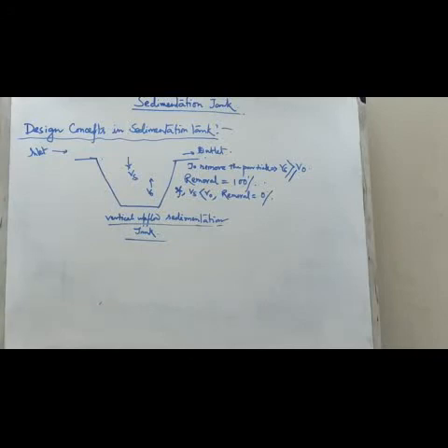Hence, for the successful design of a sedimentation tank, what is our aim? Our aim should be to fix the overflow rate at some lower value.